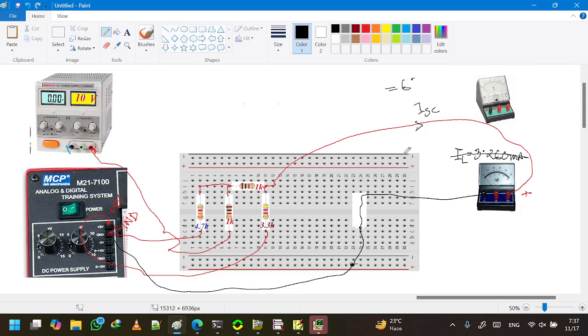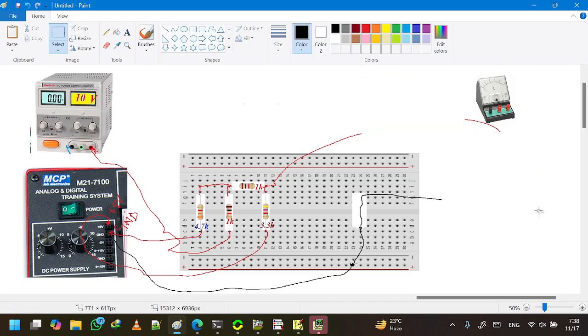It will be 6.034 milliampere, which is the Norton current, by the way. This is called the Norton current. Now, when we are done with measuring the current, we can delete all the emitters. Now it's time for our voltmeter to play.